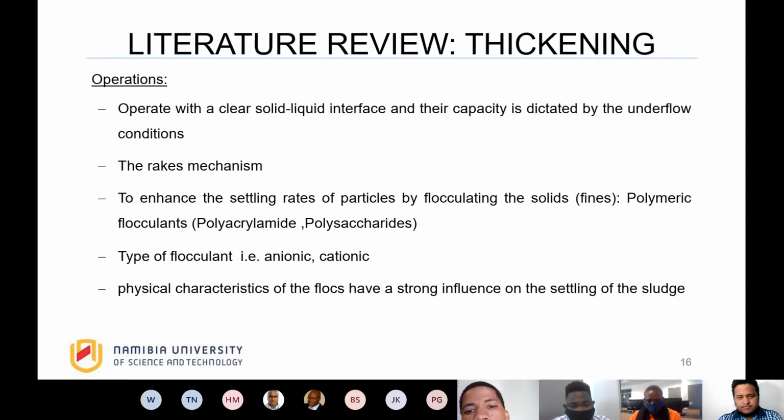So in this type of operation, the diamond recovery, we are dealing with a sedimentary type of rock. So with the test works that will be carried out, it will be advisable to carry out both the flocculation and the coagulation.